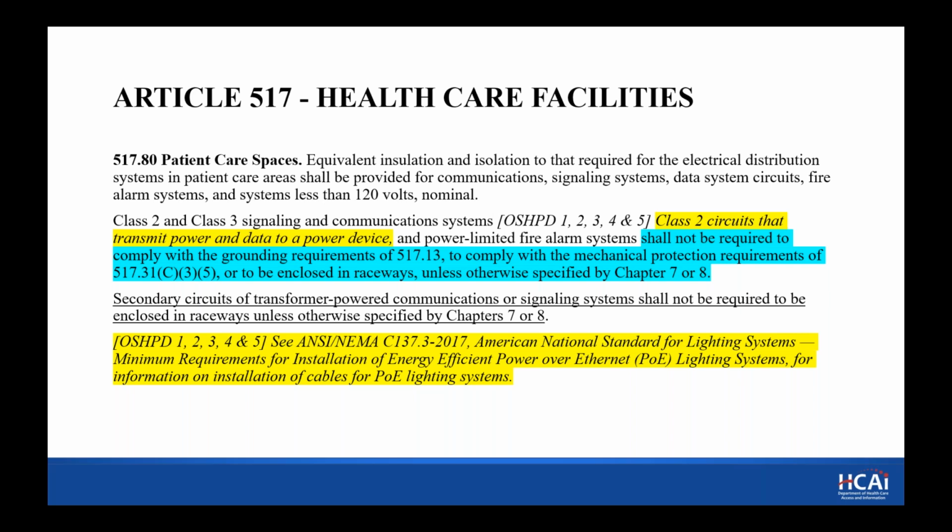It's required to have an alternate source, and that would be the life safety branch. Thank you. And the next one reads, do storage batteries on open racks require an OSP? Yes. Yep, the whole system would need to have an OSP.